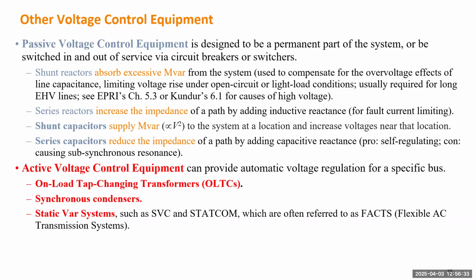So passive will be basically just based on the combination of either capacitor or reactor in shunt or series connection. On Tuesday, we finished the two capacitors, the shunt capacitor and the series capacitor. We also somehow mentioned the series reactor or shunt reactor.